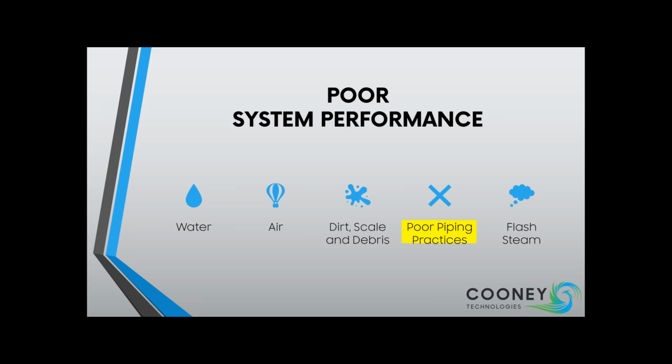You have to use the proper steam traps for your specific applications. Use the proper pipe and the proper fittings. And for contractors, don't use that 150-pound malleable 90 because you ran out of cast iron 90s. Use the carbon steel Schedule 80 pipe that would give you a longer resistance to failure due to corrosion. If you use shortcuts, they're going to catch up to you. I can promise you that. Try your best to do it right the first time.